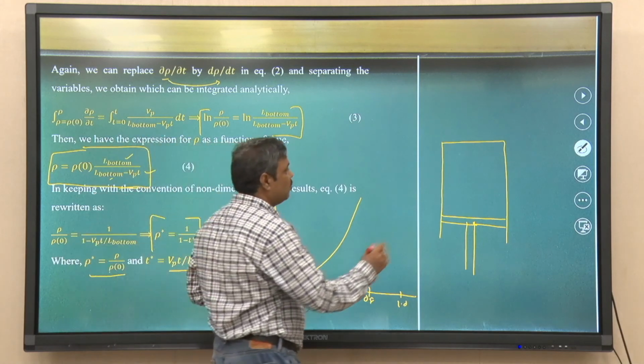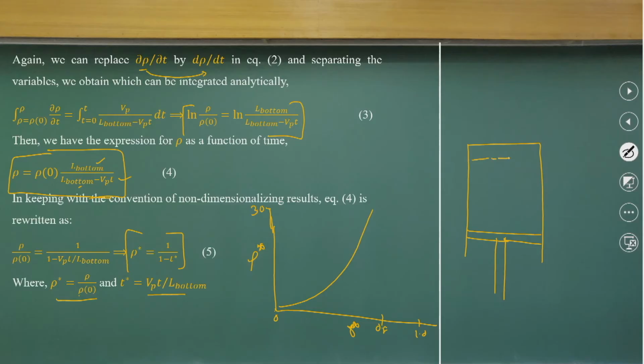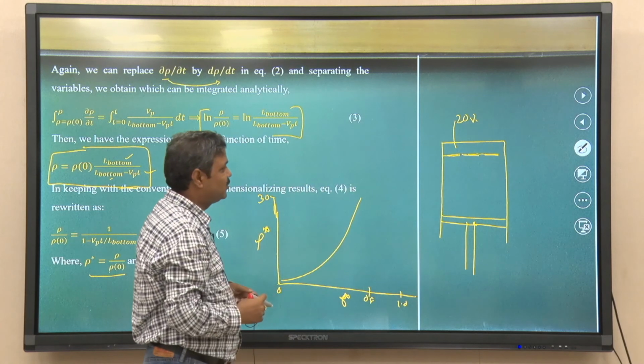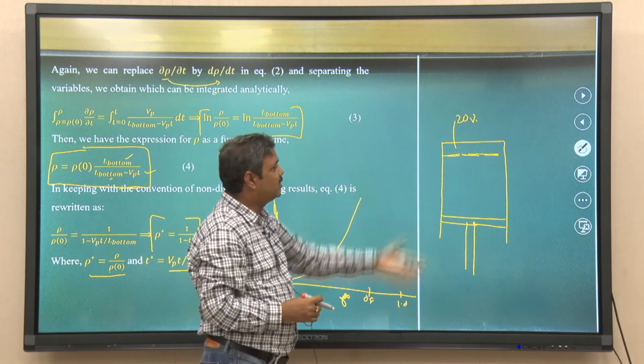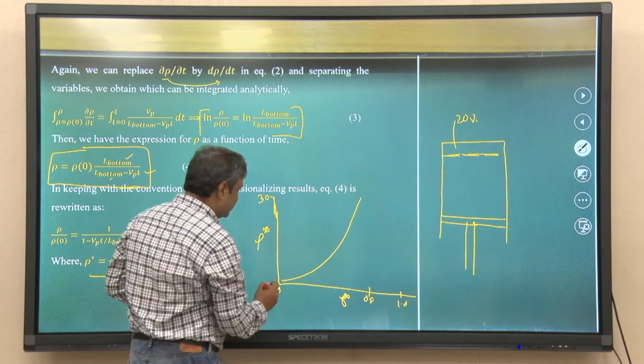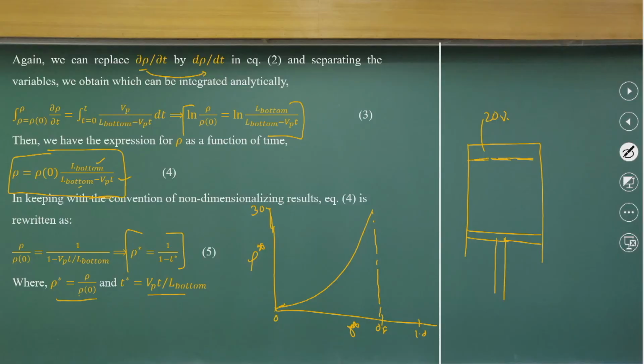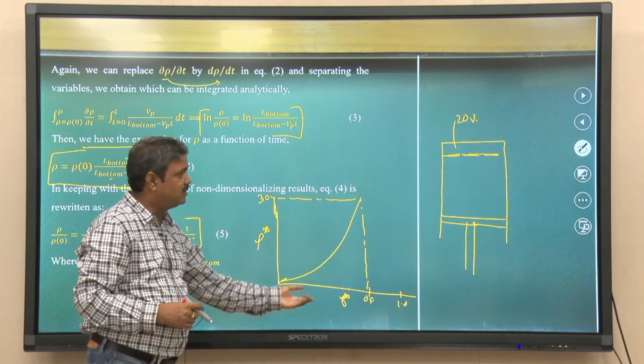That is the reason most internal combustion engines have about 20% left as clearance volume. That is how far the piston moves; that is what is feasible. We cannot make the density infinite as we compress it in a real case. That is what you can see from this figure. It goes up to 0.8, and the density increases to almost 3 times the initial value.